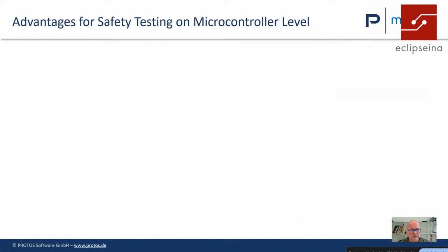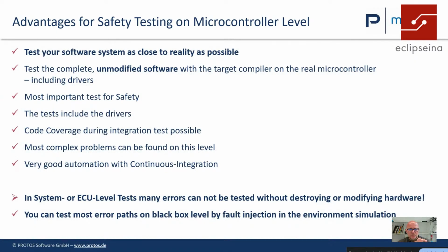Now, what are the advantages for safety testing on microcontroller level? You can test your software system as close to reality as possible. You can test the complete unmodified software with the target compiler on the real microcontroller, including all the drivers. That's a very, very good test depth.